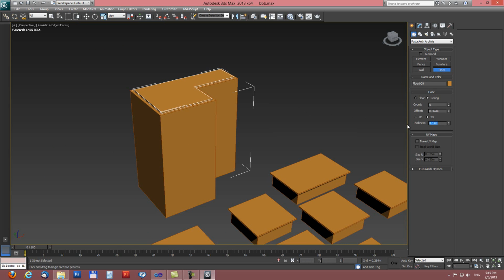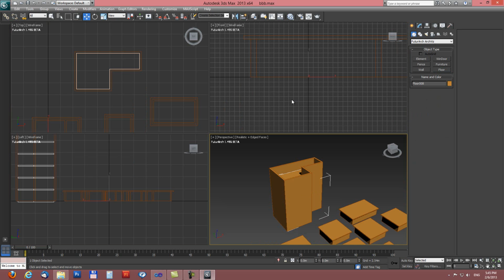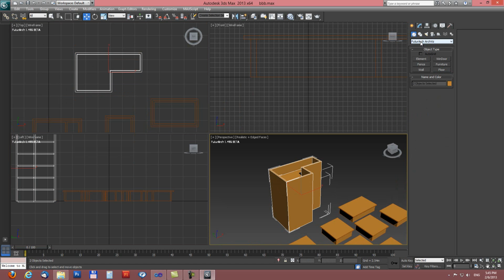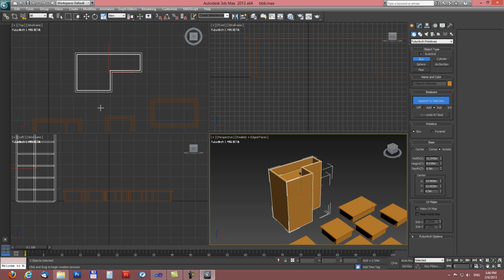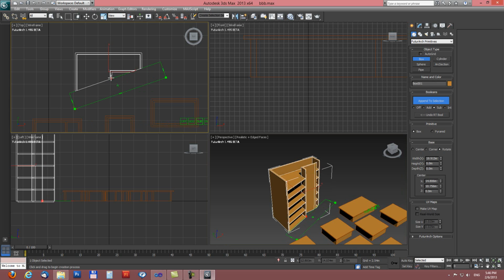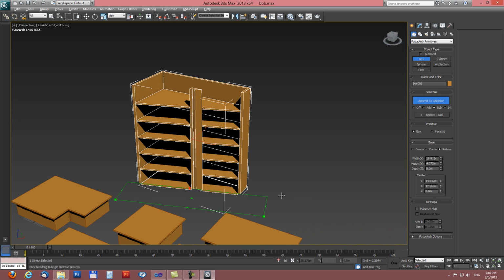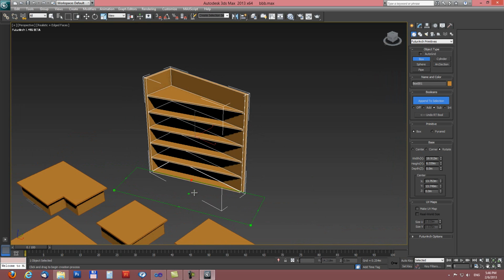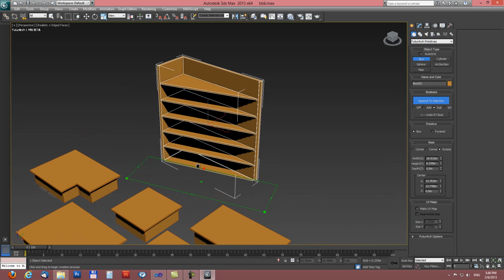So when I set now 0.2 thickness on the floor, we can see this is a very nice clean object, because when I drill it with a box tool, in rotate mode, append mode, you can see it's a very clean object, a multi-floor building. As you can see, a very quick way to create a building construction with the wall and floor tool.